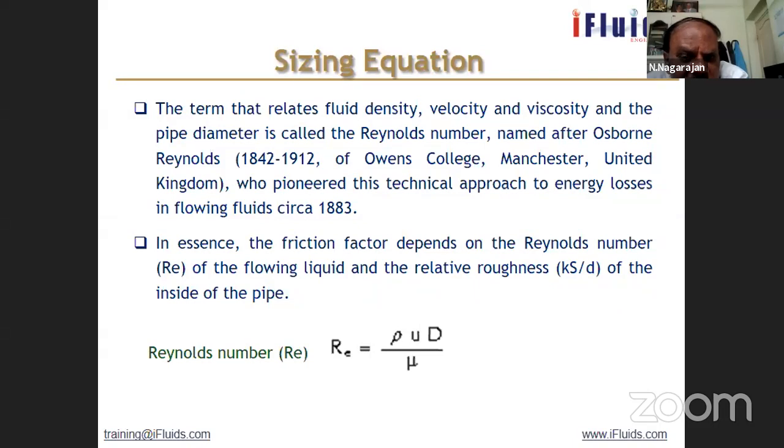That is why when you compress the gas, it becomes heated up, and that is why with compressors, we always cool the gas from the discharge of the compressor to bring it back to the suction temperature. When it goes through a number of stages in the compressor, we do interstage cooling to bring it almost to isothermal compression. Between every stage, we cool the gas to the suction temperature of the first stage. So it is almost like you are trying to make it isothermal, because with isothermal, the energy dissipation is less and it's more efficient because of its inherent nature.